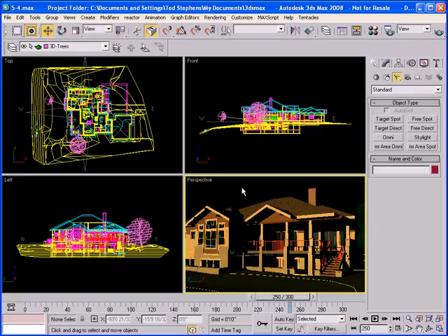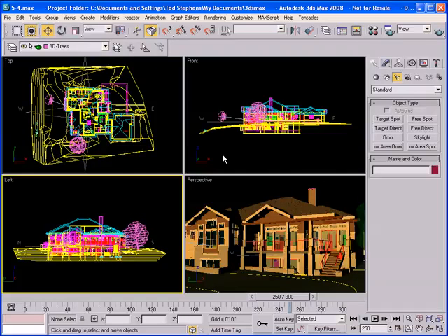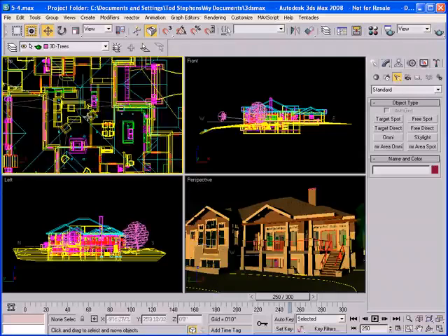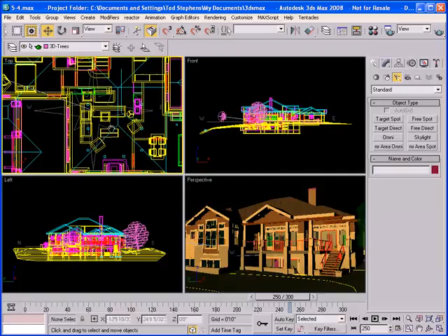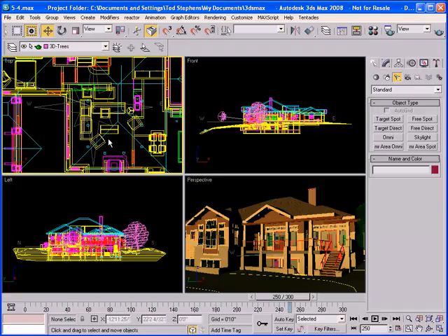And just clicking out in space there just to deselect everything. So now I'm at the proper elevation. Basically that floor that chair was sitting on, the room where the lights are going to go, now I know the top of that floor is at Z equals 0. It's at 0 elevation. So now when I put a light in here, it's going to go right at 0 elevation. It's basically going to sit on the floor of that room.